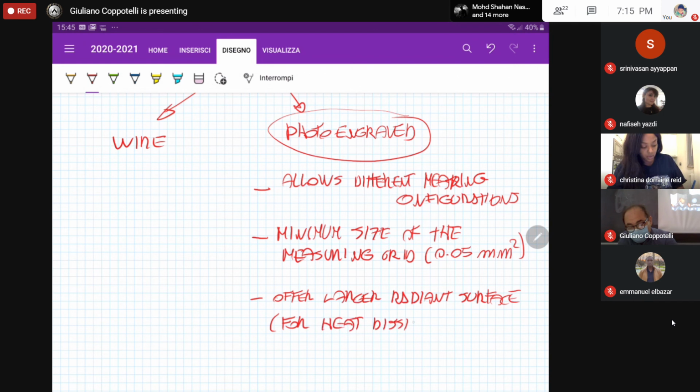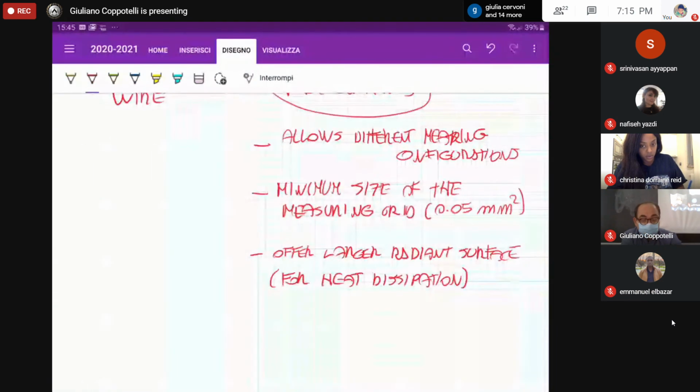As we can see later on, the strain gauge measurement requires the connection of this strain gauge to a measuring circuit. We will see later in a few days what happens. But before entering into details, let's assume that because we have this measuring circuit, we need to dissipate the heat that could be generated because of the Joule effect in this measuring device. Okay.